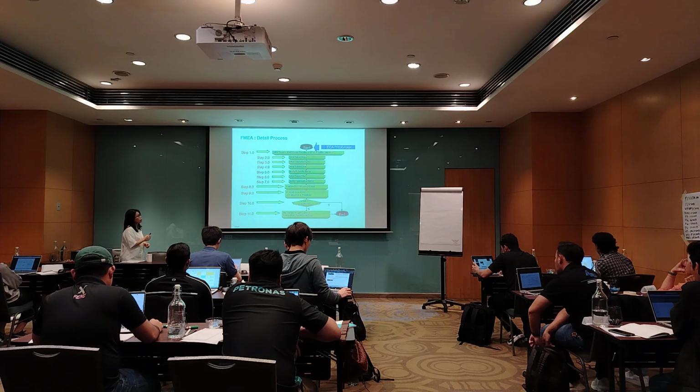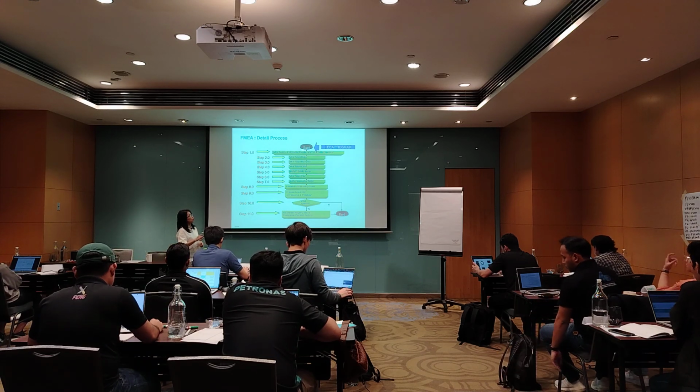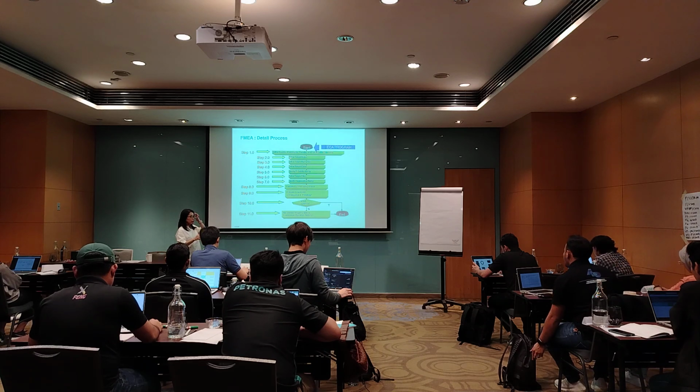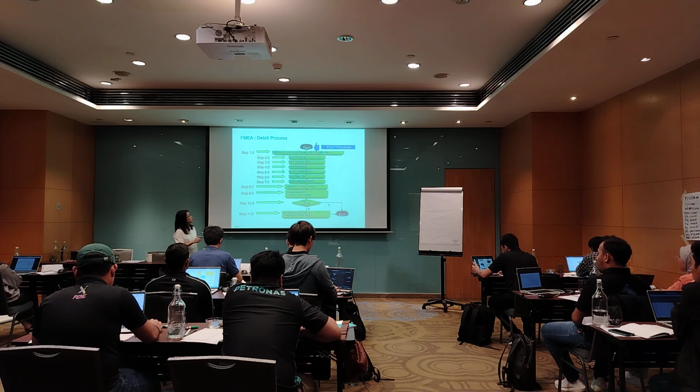All right. Again, this is just the step. When you perform the ERS or FMEA, first you know your criticality. Ask, is this critical enough to do FMEA or not? Or is it just a C3 equipment? Define equipment information, boundary and function. Then failure modes, mechanism, cause, probability rating.